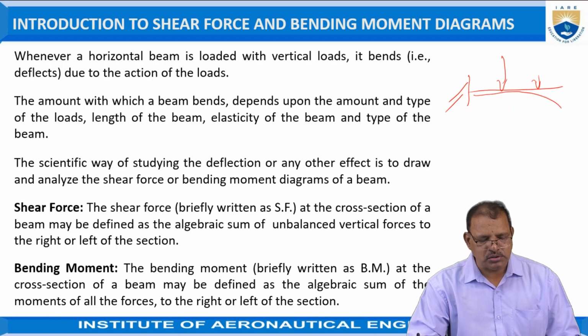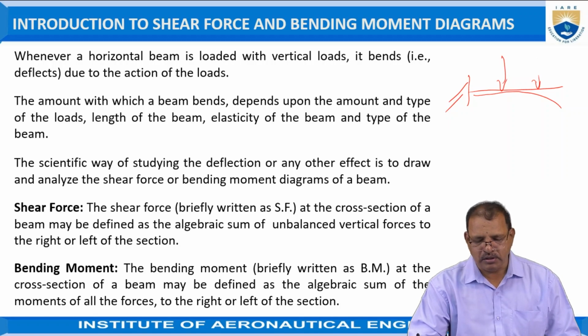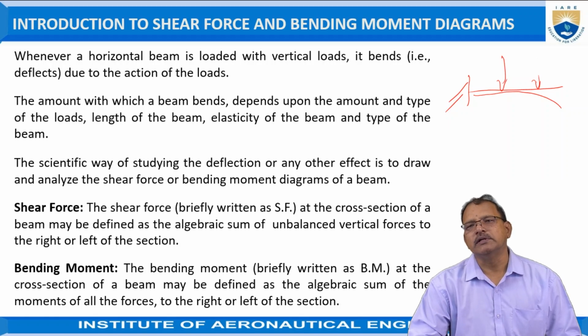The shear force is a vertical balanced force with respect to the left or right of the section. Generally, it is treated as the algebraic sum of the unbalanced vertical forces which are acting on the beam when we are considering from the left or right of the section.